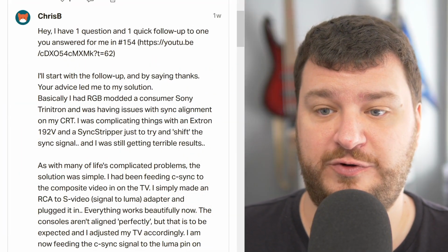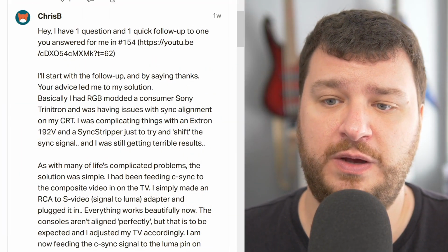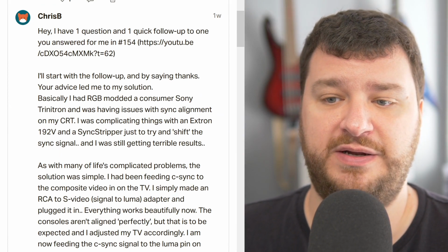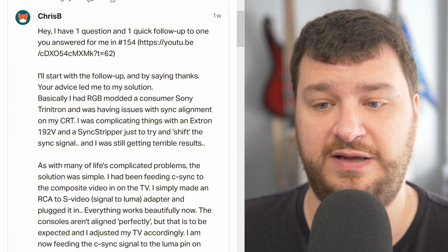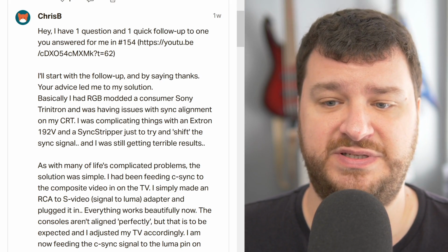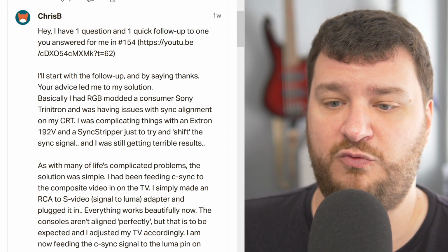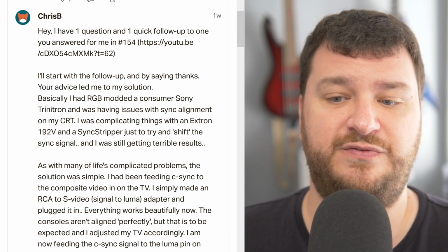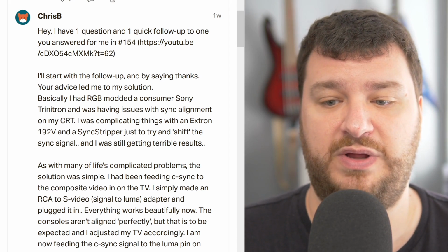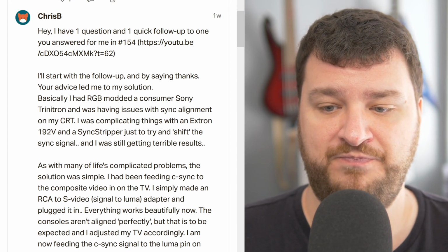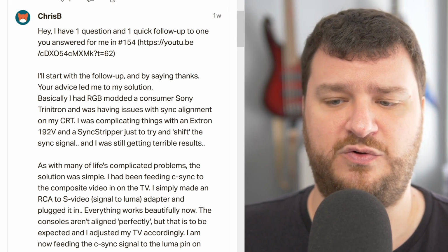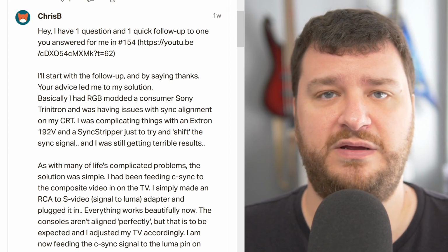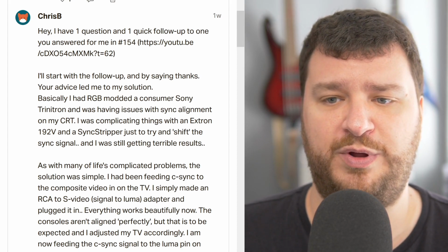A couple of things from Chris B. First, they were following up with a question about an RGB modded consumer-grade Sony CRT, and I guess they were having issues with sync alignment, and they found that running the sync through the S-video line instead of the composite video line seemed to align things better. They also think that there was a ground issue, so it could have been a combination of both.